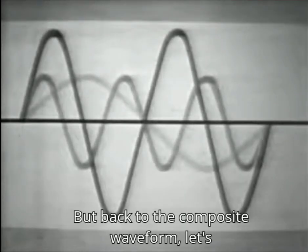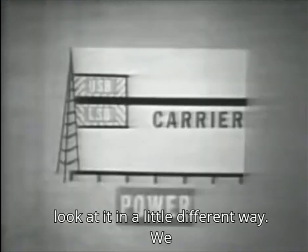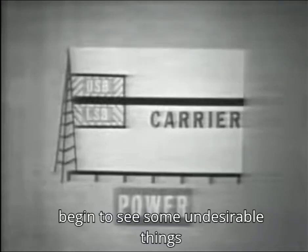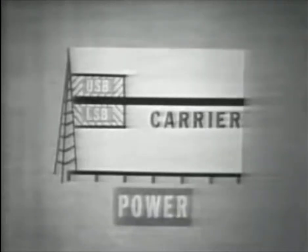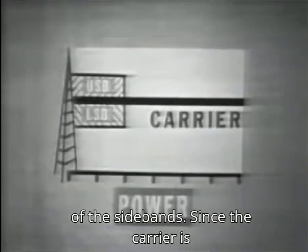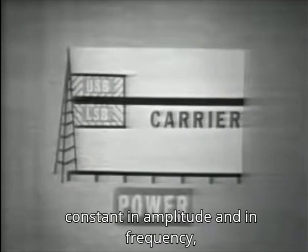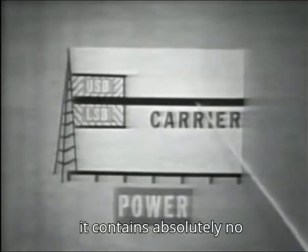But back to the composite waveform. Let's look at it in a little different way. We'll begin to see some undesirable things about the conventional AM signal. After the sidebands are generated, the carrier is not required for transmission of the sidebands. Now, since the carrier is constant in amplitude and in frequency, it contains absolutely no information at all.